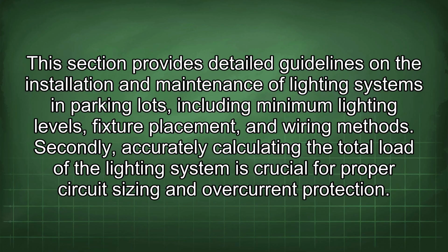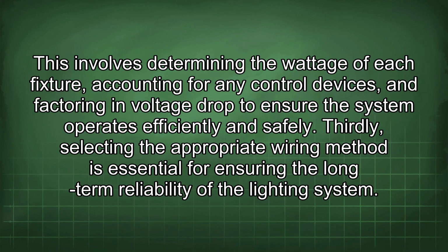Secondly, accurately calculating the total load of the lighting system is crucial for proper circuit sizing and overcurrent protection. This involves determining the wattage of each fixture, accounting for any control devices, and factoring in voltage drop to ensure the system operates efficiently and safely.